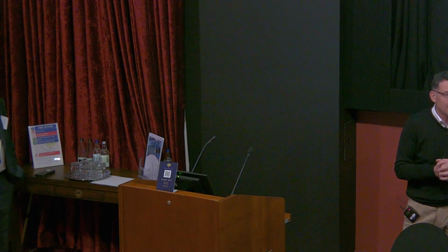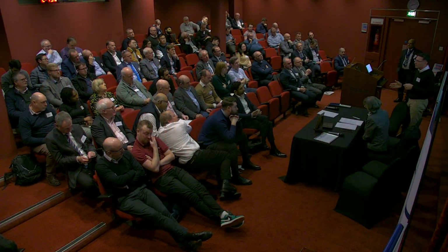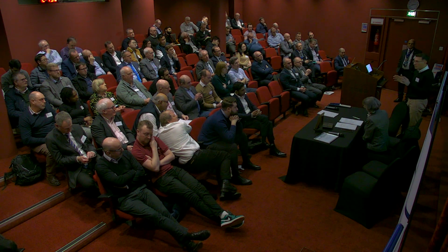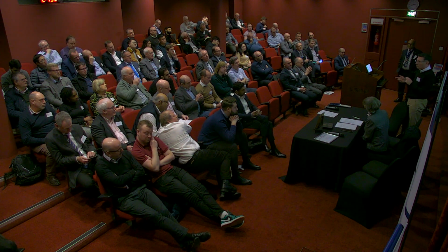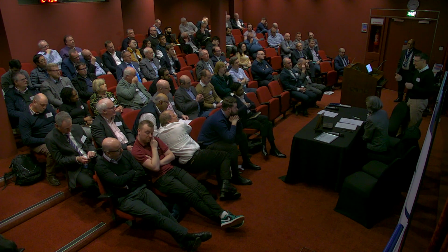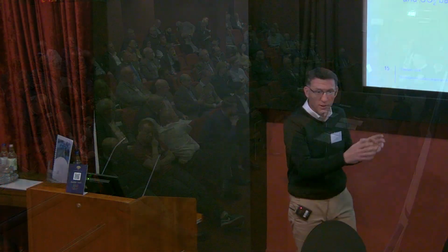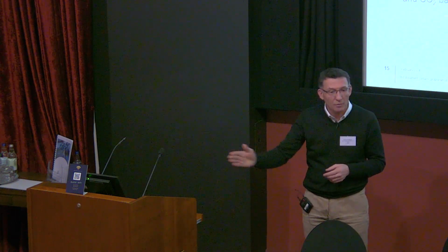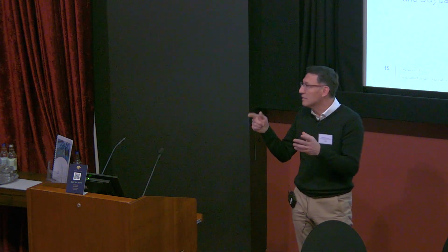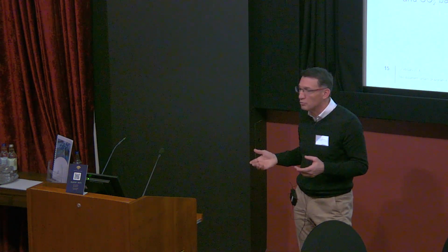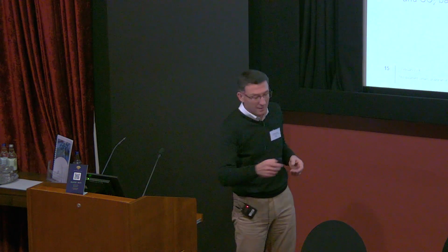And what do we see? They want to switch from a CEM I 52.5 to a CEM II/A-L 42.5. Since the beginning it's not easy. And they want to switch from two sands to one sand and a crushed sand. So we have a tool like that to benchmark the sand and to see the water requirement. We cut the formulation at the coarse aggregate, and we only focus on the mortar part. The concrete is an S3 consistence concrete. So when you do that, what do you obtain? Well, you obtain that.